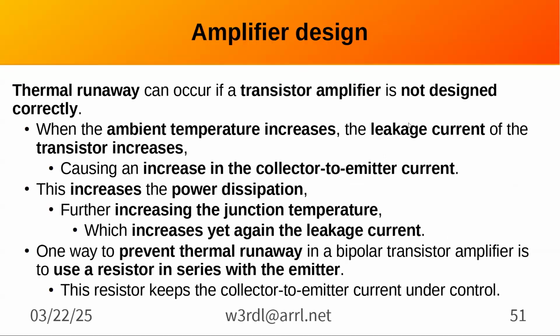Thermal runaway, if you've got a transistor amplifier, is a problem because solid state using silicon, I'm not sure that the other semiconductors don't have the same problem, but silicon decreases resistance as the temperature goes up, where in a normal conductor, the resistance increases as the temperature goes up.